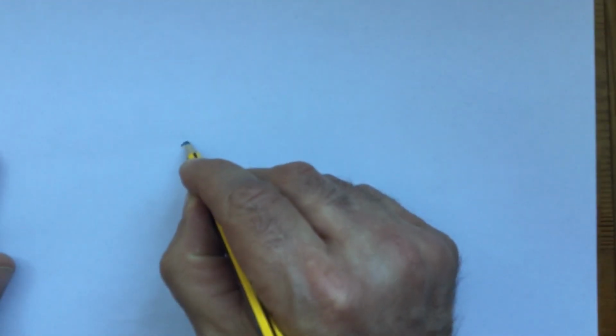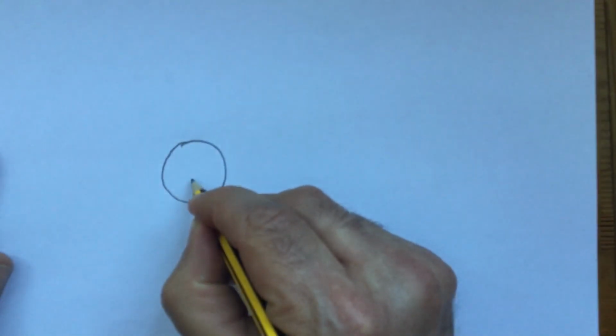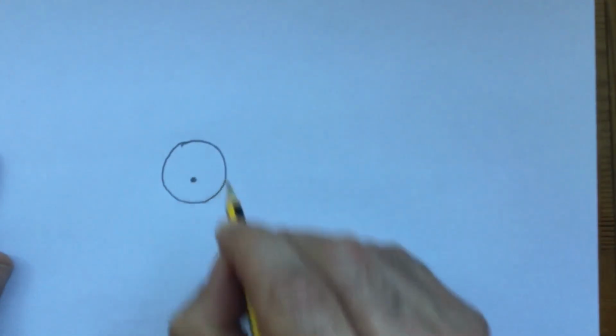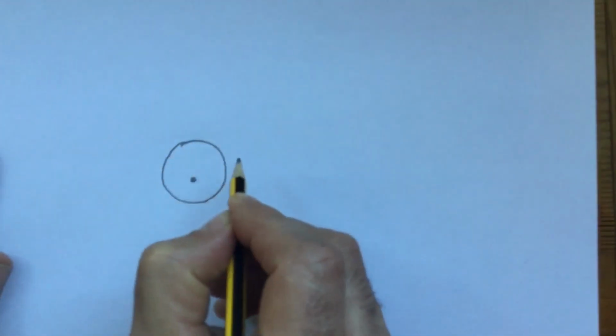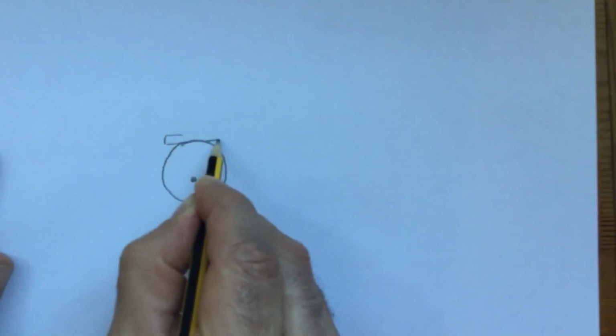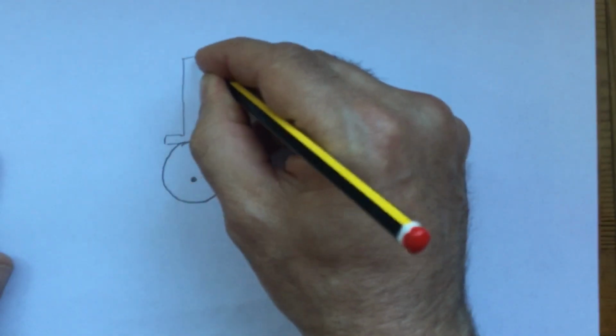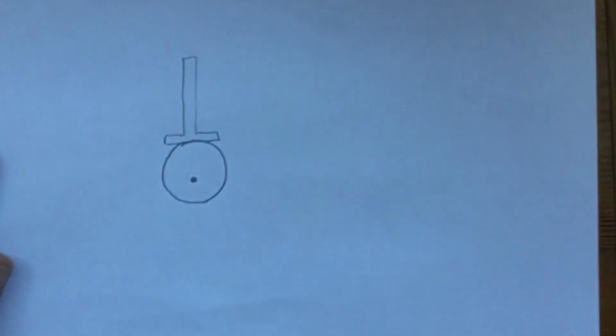The first cam we looked at is called the eccentric cam, and I wanted to draw that for you so that you understood what it was. What eccentric means in this sense is something that's circular, but the shaft isn't quite in the centre. So when you've got the follower on top of it, it will rotate off centre and push the follower up and down.